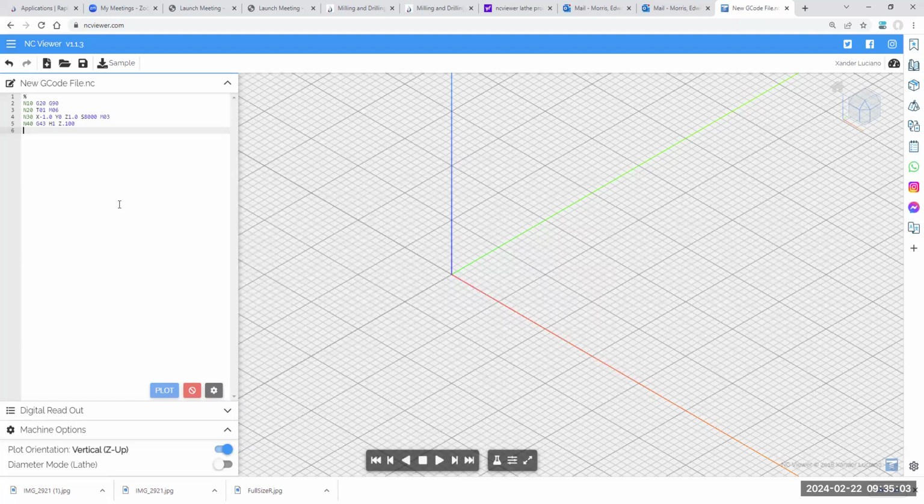That will be stored on the CNC machine you're actually using. Then we're going to go linear. Don't worry, we're going to go through this again. I'm just trying to get it typed up right now. N50 G01 Z -0.125 F10.0. F is your feed rate at 10 inches per minute.